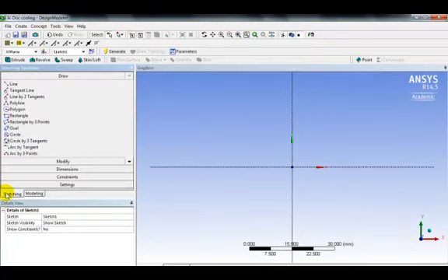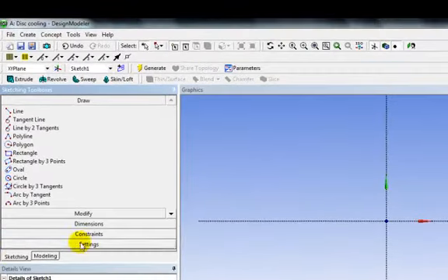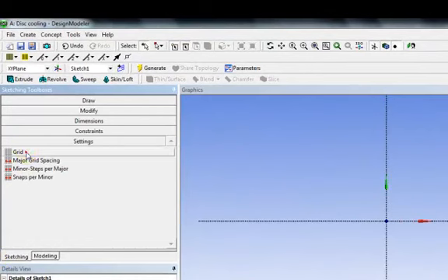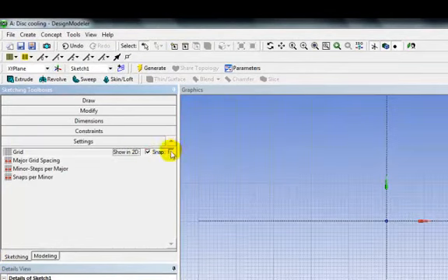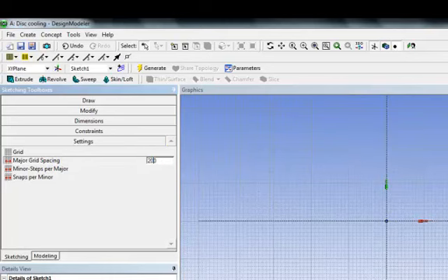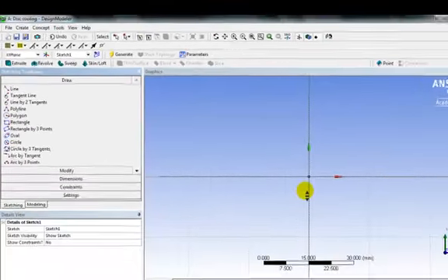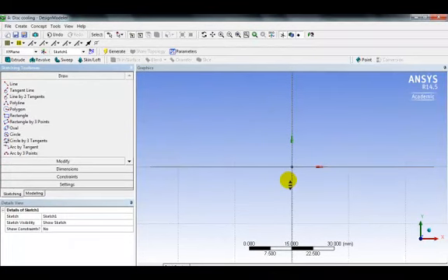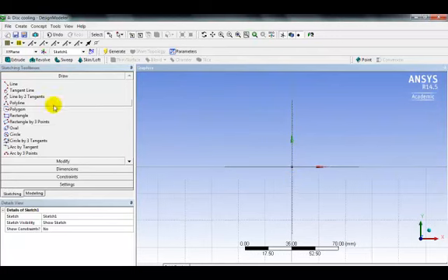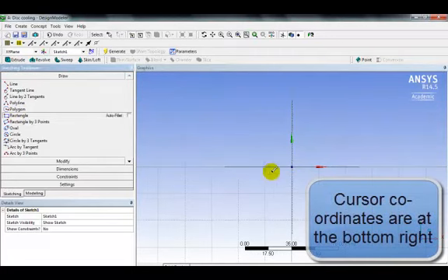We're going to do a sketch of a circle and a square, and that's going to be used to create the domain. So first we're going to do the square. Settings, grid, 2D, snap to grid, major, we're going to do I think 200. Minor doesn't really matter. So we want to draw, I want to zoom out a bit. Maybe there. And we're going to do a rectangle for the main domain.